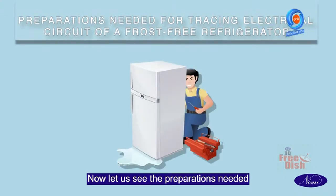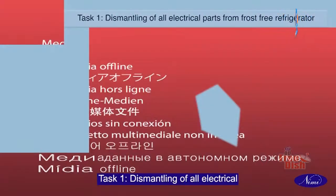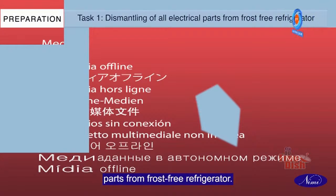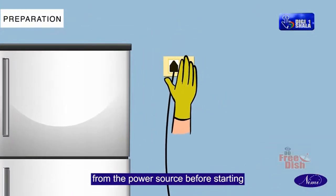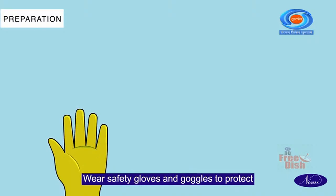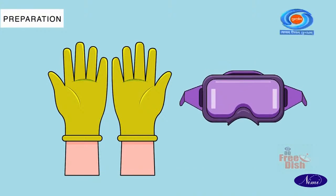Now, let us see the preparations needed for tracing the electrical circuit of a frost-free refrigerator. Task 1. Dismantling of all electrical parts from the frost-free refrigerator. Ensure the refrigerator is completely unplugged from the power source before starting any dismantling work. Wear safety gloves and goggles to protect against sharp edges or electrical hazards.